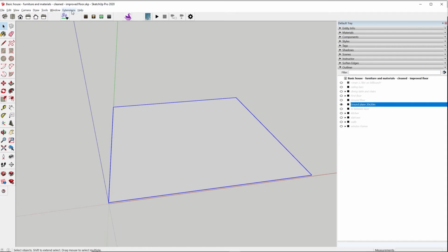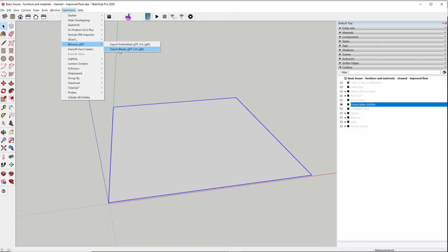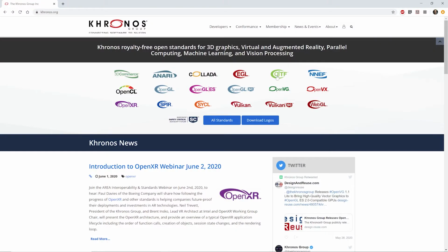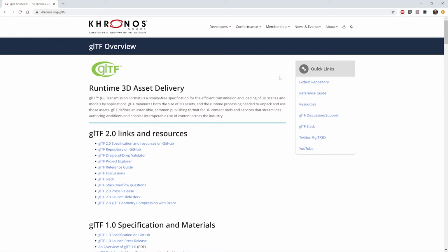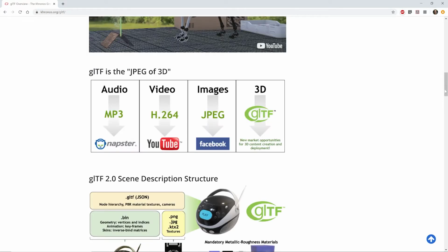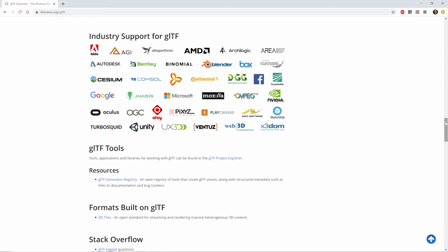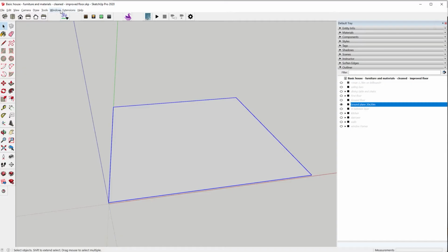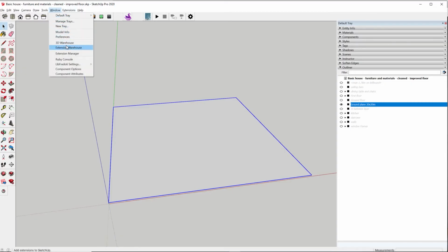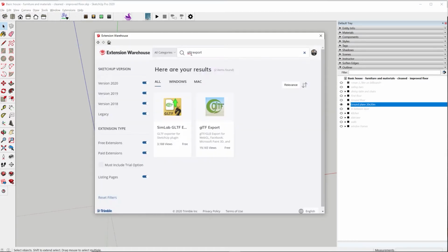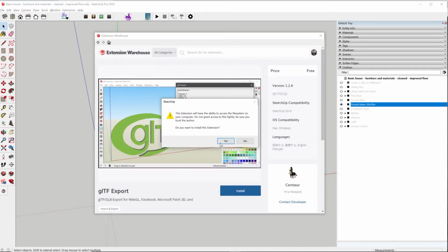We'll first need to go back to SketchUp and create a plane that's around 20 meters by 20 meters. Make sure to save the plane in a GLB file format, a relatively new file format seen as a successor of Collada. While GLB files are not widely used in the CAD industry, it is the only 3D format supported by the Spoke editor in Mozilla Hubs. So in SketchUp, you will need the GLB export plugin that's available in the SketchUp extension warehouse. You can find a link for this plugin in the video description.